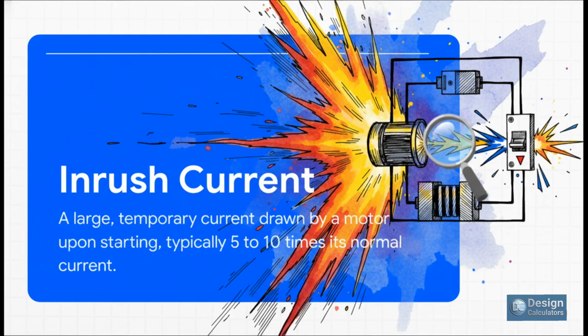Okay, so what is inrush current? Well, when a motor first starts up, for just a moment, it acts kind of like a transformer with its secondary shorted out. What that means is it draws this massive spike of current. We're talking 5, 10, sometimes even more times its normal running current. Now, your standard circuit breaker sees this huge sudden spike and thinks, whoa, short circuit, and it does its job. It trips to protect everything. But here's the kicker. For a motor, that giant spike is completely normal.